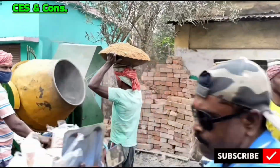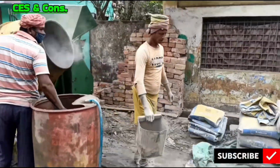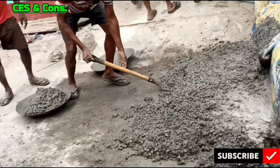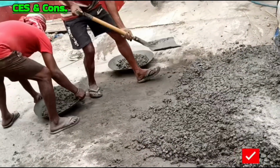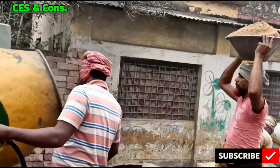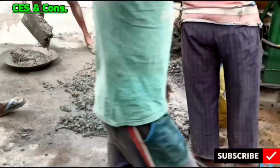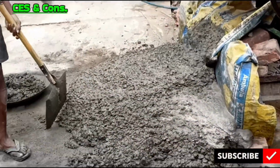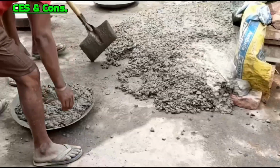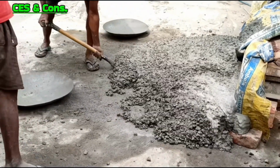Before preparation, ensure that the drum is clean, free from hardened concrete or any debris. Loading sequence of materials in the machine has been suggested in the Indian Standard Code of Practice 456/2000 in clause number 13.2.1. It stated that first place coarse aggregate inside the drum, then add fine aggregate, that is sand, next add cement. Finally add water, preferably through a measuring device. This sequence avoids cement sticking to the drum and ensures uniform mixing.